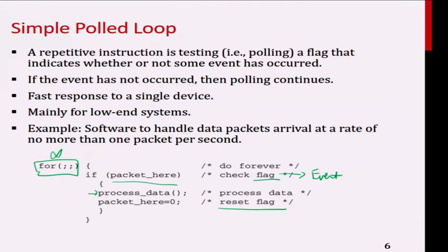And this may repeat itself n times, depending on how many tasks you have to cater for, because every task will trigger some event. While you are moving your robot, for example, the encoder from your wheel disk is going to come in. But at the same time, a message on the Bluetooth channel may come in. So I just have a loop and I keep checking which one happened. As long as any event triggers, then I go and cater for that particular event. So this is a simple poll loop.